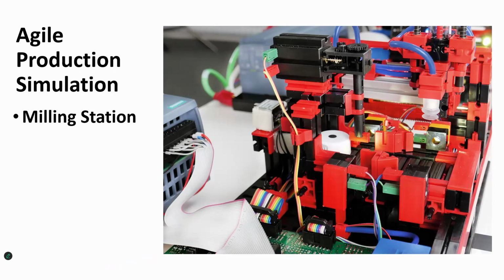So continuing along, the milling station consists of a docking station, again, for the AGV to come up to, and it again has a vacuum gripper that will take the workpiece from the AGV and place it onto a conveyor belt, where it is transported, in this case, under the milling machine. There, the milling of 2 pockets on the workpiece is simulated, and after this process occurs, the workpiece is placed back onto the conveyor belt at this station and transported back to the gripper robot, which again will move this piece back to the AGV.